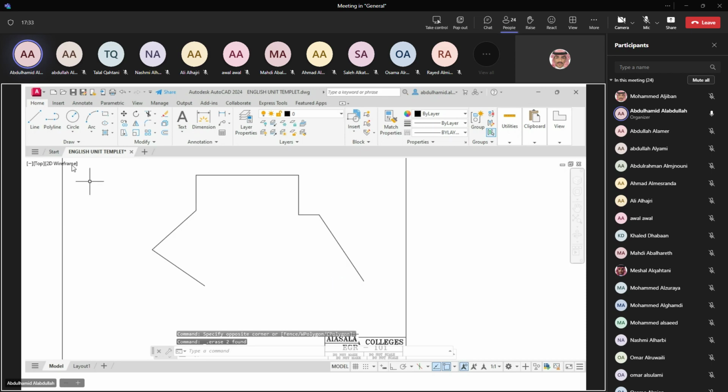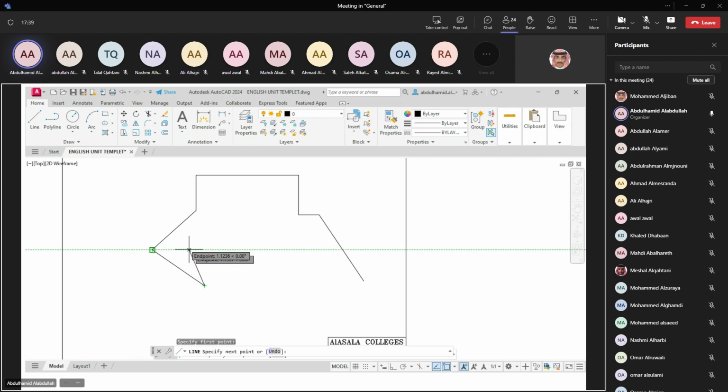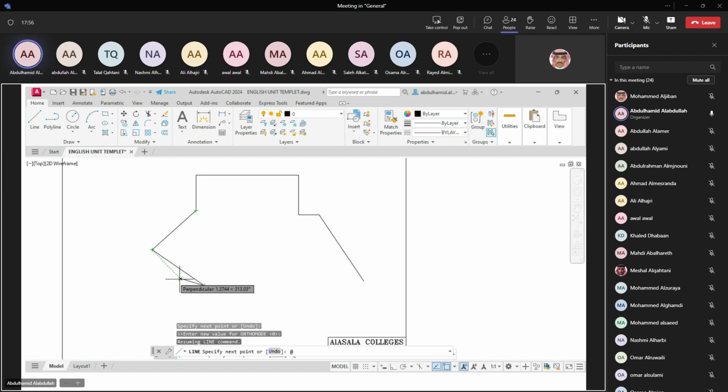Simply, from the starting point, to do the angle over here, you don't need to do any calculation. You can use the Cartesian method, which is whatever the value for X, but this time, because I am going to go left, I need to make it negative. Let's put numbers. So -1, for example, that's the value for X, comma, what's the value of Y? It is given as a dimension. Let's say it is 2, for example.